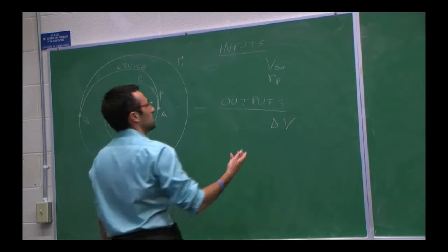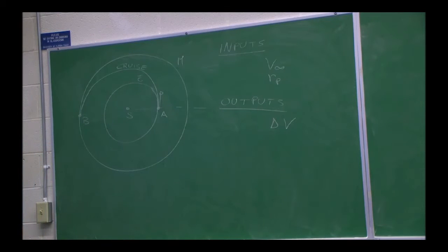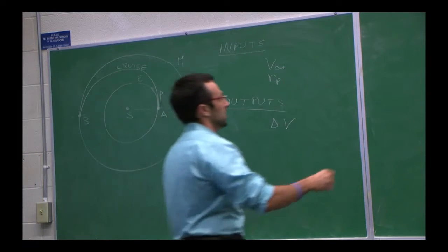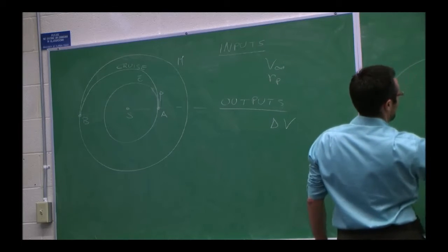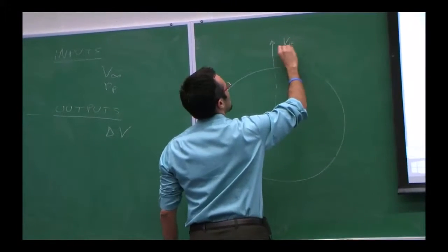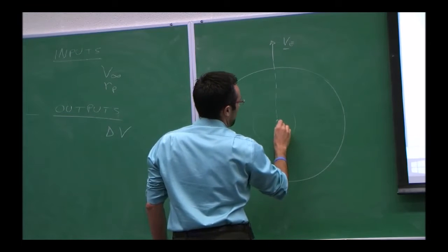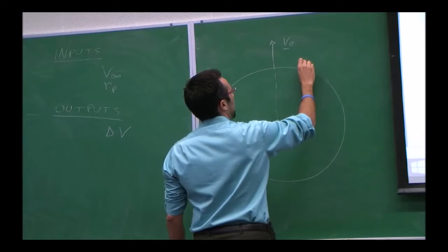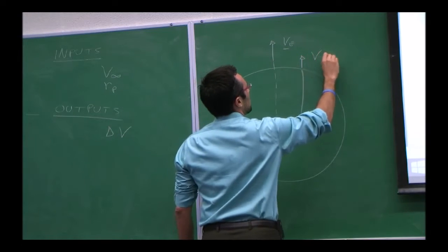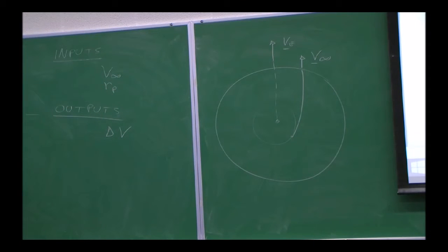What else do you need to figure out? You're performing a maneuver, right? I'll probably do a little sketch here, assuming that I'm good enough to reproduce what the book has. So this will be your planet Earth, its velocity, and you are on some parking orbit here, and at some point you decide to go on this hyperbolic path that has to lead you, in this case, to leave the sphere of influence with a V infinity that is aligned with the velocity of the planet.